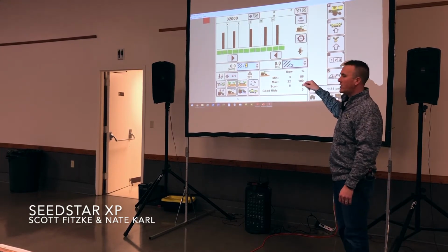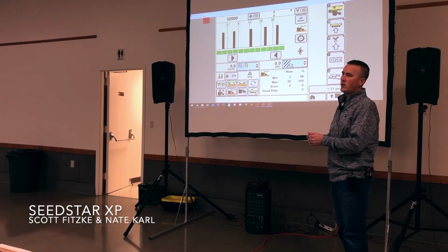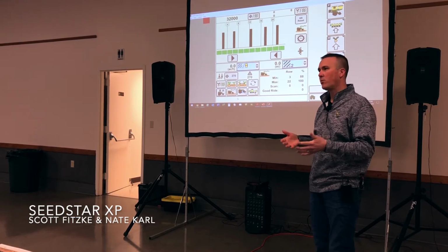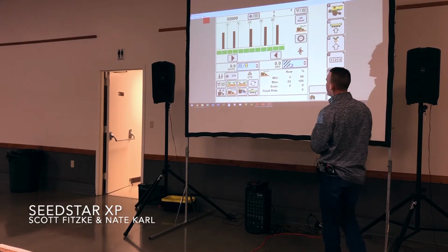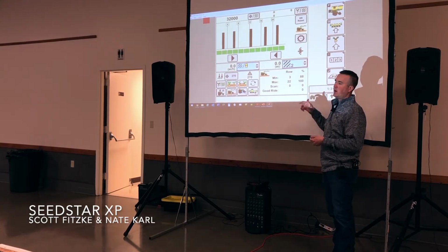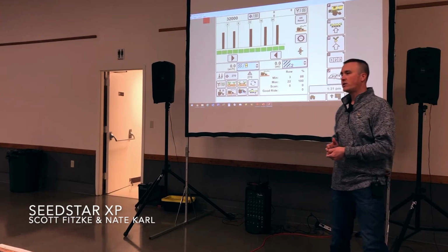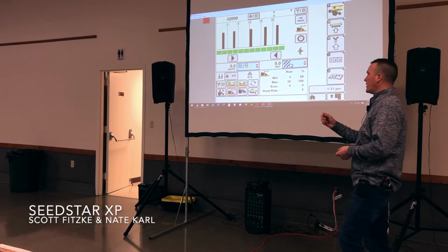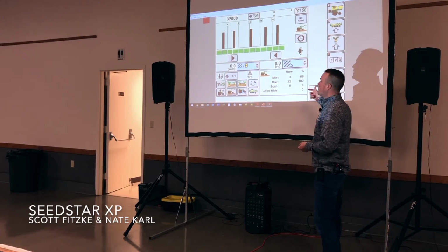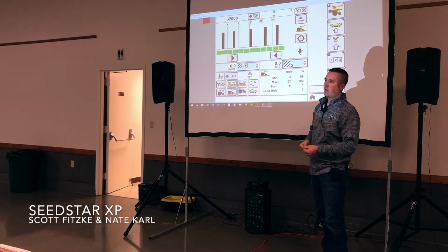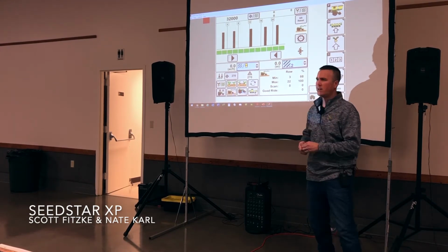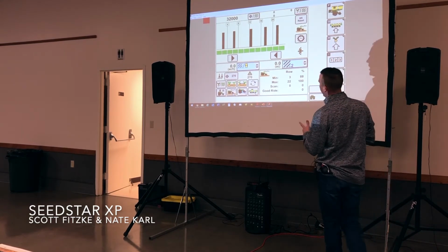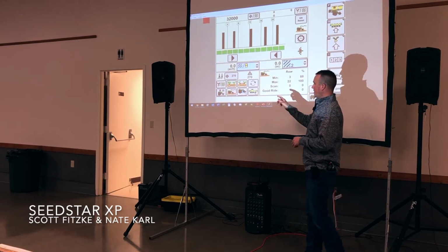So, in summary, I would not get too aggressive with pushing down on weight, just like you wouldn't in any other scenario. You should be walking back and digging to make sure we're not pushing down and causing a bunch of compaction issues. And then coming back and monitoring that ride quality and keeping that above 90%. There's times that maybe we need to be going 3 miles an hour because we're in a really rough area of the field. And that ultimately is what's going to give us a better ride and a better seed placement, as opposed to just pushing harder down on that row unit. Again, like I said, they talk much more in depth in the downforce class, but that's really what we're after with those adjustments. Next box, please.